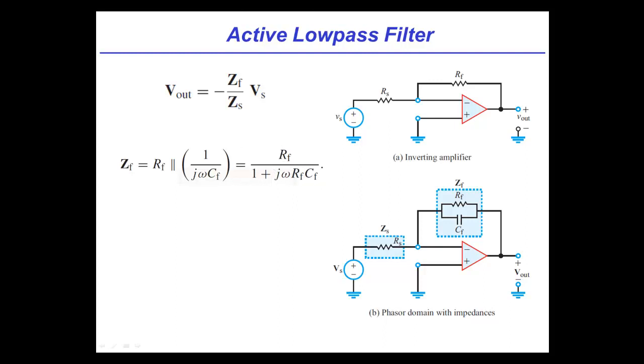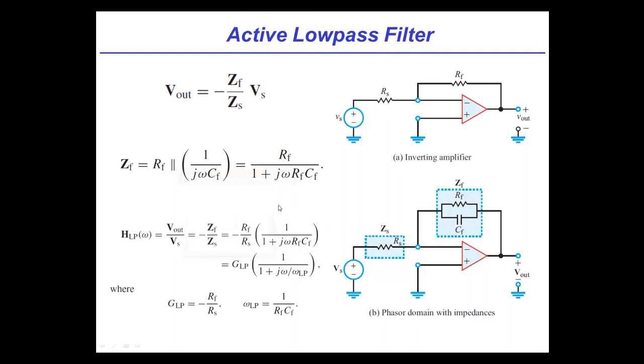Okay, so you'll notice, now, seeing this, Michelle, you should automatically recognize that this is therefore going to be frequency dependent. Oh, that's right. So your Vout over Vs is going to be frequency dependent. Right. Okay. And in fact, if you look at this, given that the gain is supposed to go up with ZF, whereas if I look here, ZF goes down with frequency, I would expect the gain to drop with increasing frequency. Oh, I get it. So basically you can build an amplifier with a gain that changes with frequency. Exactly. That's the basic idea. This is an amplifier, the gain that changes with frequency.